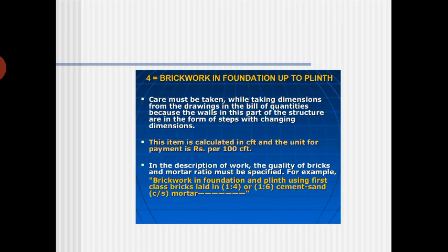Of course, next is brickwork in foundation up to the plinth level. You already know what the plinth level is and what the execution level will be. Care must be taken while taking the dimensions from the drawings in the bill of quantities, because the walls in this part of the structure are in the form of steps with changing dimensions.